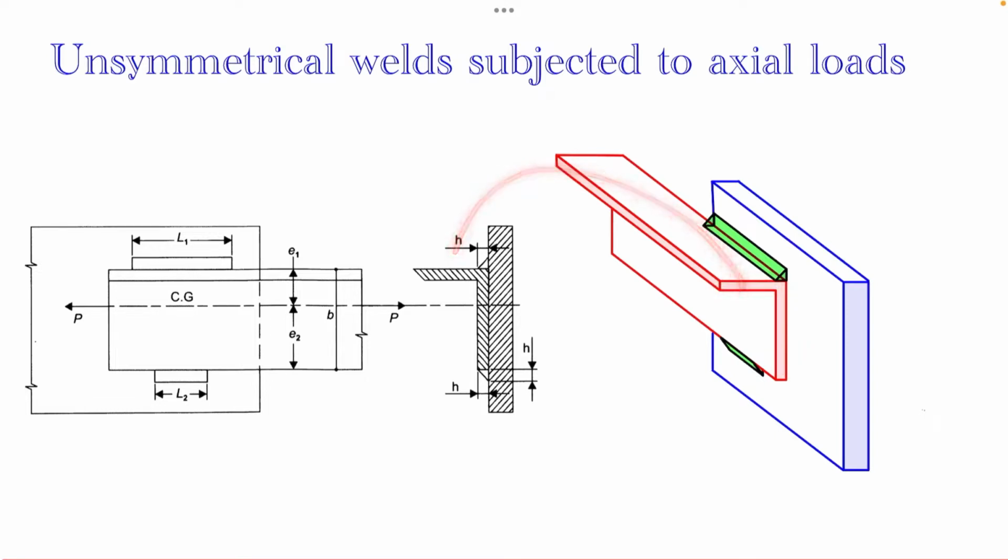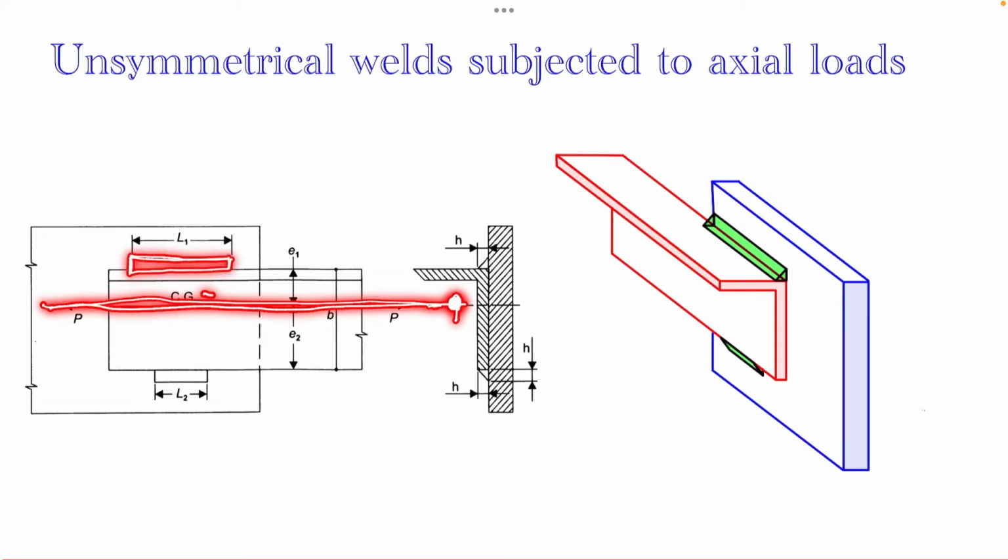That means this weld section will have the cross section in the shape L, with a CG somewhere at this position. The load perpendicular to this plane will be acting along this line, that means through this CG. Whenever the load is passing through the CG, the weld near this CG will take more load, so the weld line near this location should be longer compared to the other. Anyway, these weld lines are of unequal length.